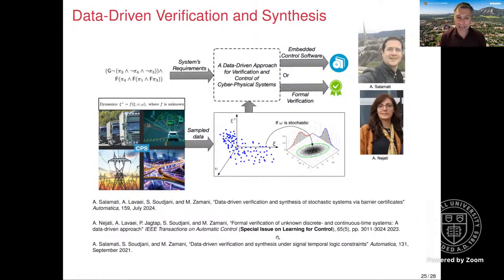So what we do here, we generate input-output data from the black box model of the system. We initialize the system, we put a bunch of IID samples inside the state set, and we simulate the system starting from those data points. We let the system evolve for 1 unit of time, and we look at the output. So I have capital N input-output data. Now I am asked, can I use those data directly to generate a barrier certificate?